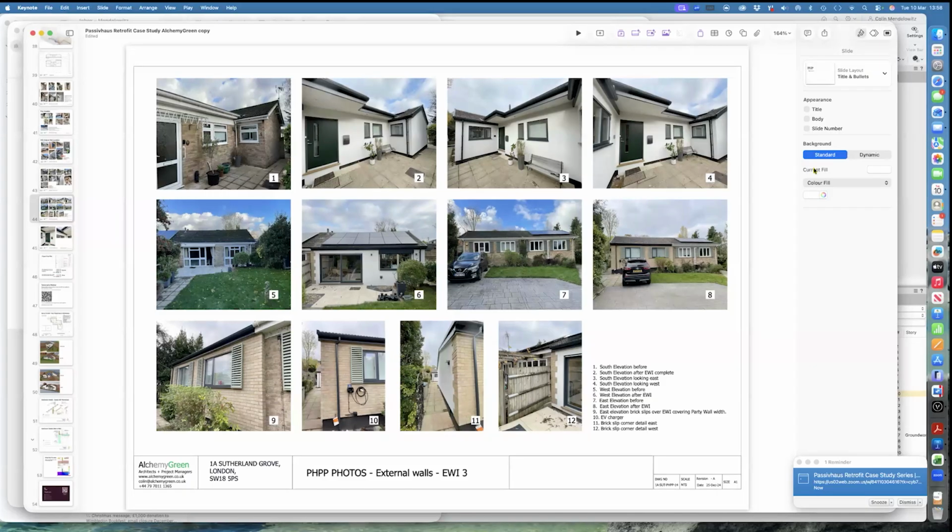The last thing I'd say about the EWI is, in those pictures, we dug out the perimeter so that the EWI could go down into the ground, and then did the block paving at the end after all these photos were taken. That gives you a very warm feeling of confidence about how you've looked after your DPC and everything else. That's one of the big risks in retrofit: are you looking after your DPC? And your void, if you have one; this doesn't have one.